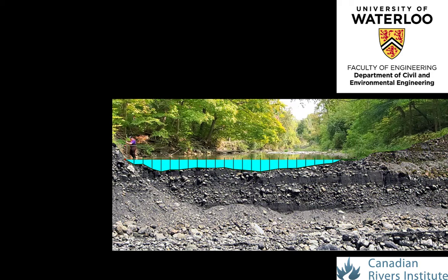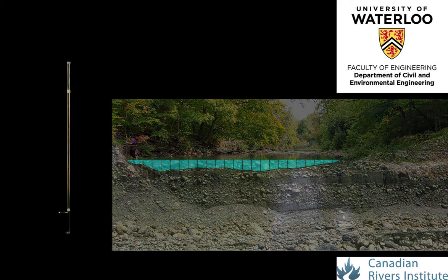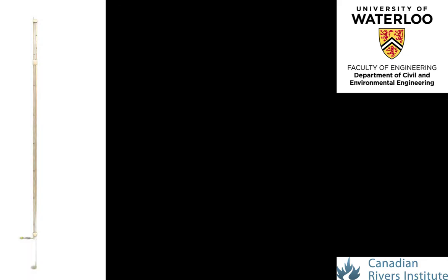Finally, prior to undertaking the field velocity measurements, an explanation of the functioning of the topset measurement rod is merited. There are various versions of this rod depending upon the flow meter or sensor being used, however the application is generally the same. The topset rod is used to specify the depth or depths from the bed of the channel at the given panel location that the velocity measurements are made at.